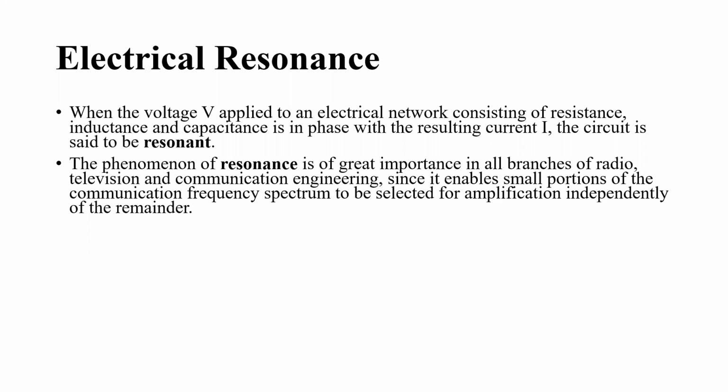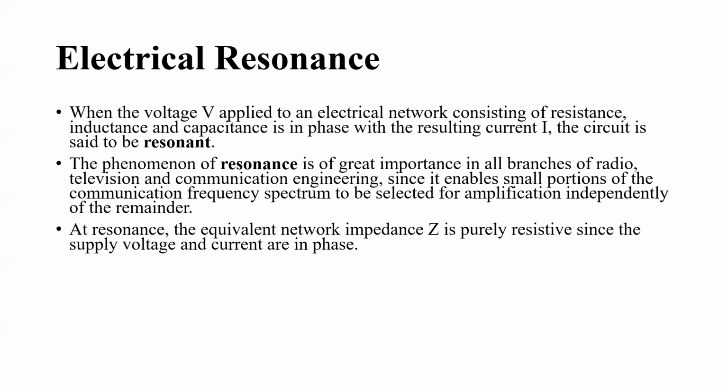The phenomenon of resonance is of great importance in all branches of electrical engineering, such as radio, television, and communication engineering, since it enables a small portion of the communication frequency spectrum to be selected for amplification independently of the remainder. At resonance, the equivalent network impedance Z is purely resistive since the applied supply voltage and current are in phase, and the power factor of a resonant network is unity.